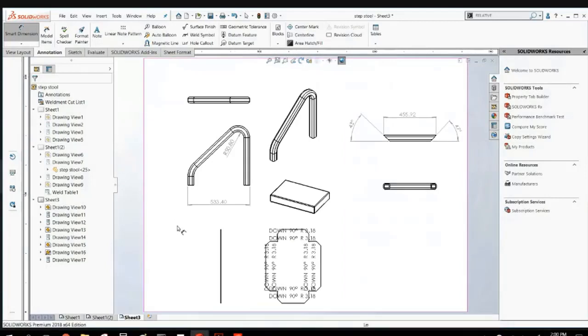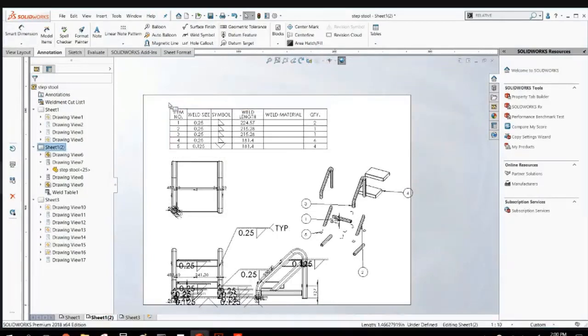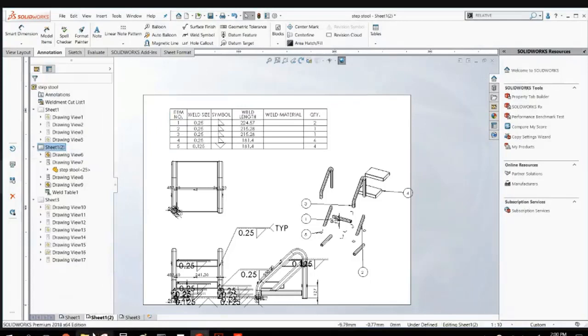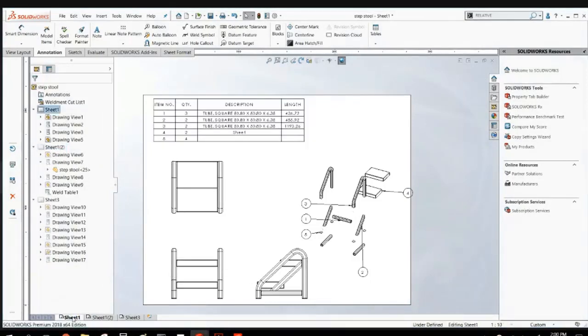So, okay, those are really the basics of weldments. Using your weldment tools, create sheet metal in there. You can even extrude any shape you want. It's just a multi-body design, and you're able to grab information like a weldment cut list is automatically set up for you. Getting a weld table like this, you have to set up those welds ahead of time physically in the model.